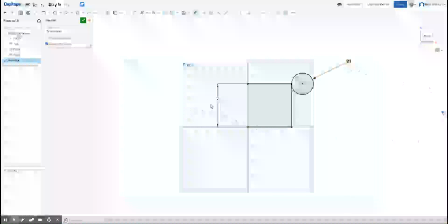So what I want to do now is just see where are all the things that I've defined in this sketch. So if I click Show Constraints here, you'll see here's my equals, here's my vertical, horizontal, horizontal. Those were all those auto inferencing that it did. There's my tangent that I created. There's my horizontal. You'll notice that when I mouse over them, it tells me what things are equal. So if I mouse over these, you'll see that they're equal. You'll see that this is a perpendicular. And so it highlights the things that are included in that constraint.